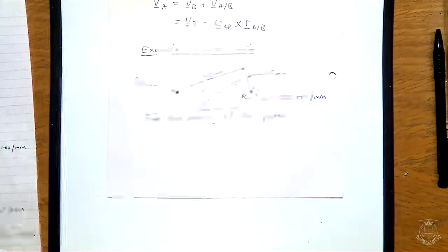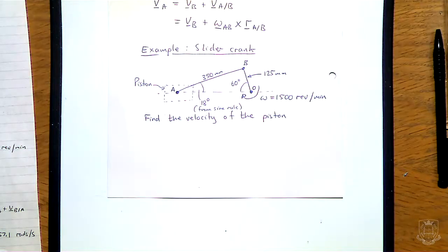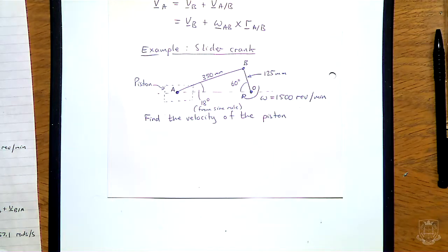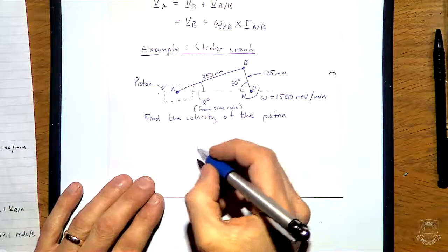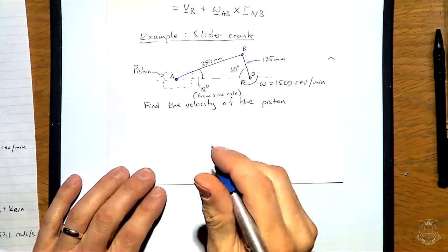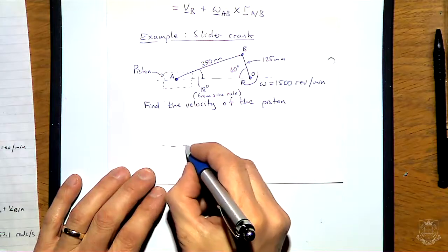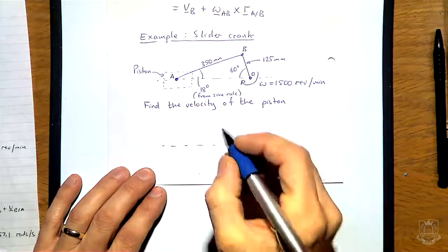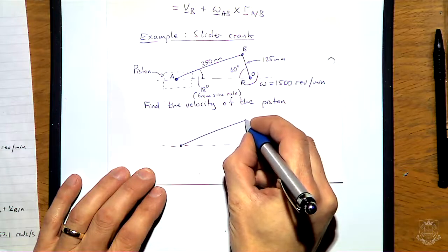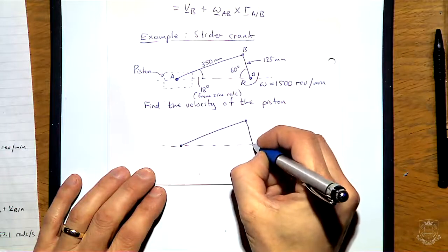So that's straightforward. But what we need to do from this diagram is come up with a diagram which relates our vector algebra and the velocities at A and B together. So what we're going to do is redraw the diagram in terms of the velocity components. So we'll sketch it out like this. We have point A here, point B there, and the origin O here.